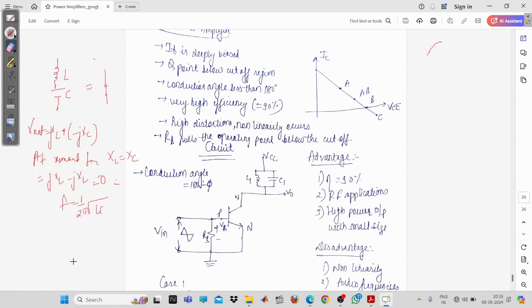Or you can understand the concept from the curve also. We will take the impedance versus frequency curve. This is the frequency. We are increasing our frequency from the DC value, that is 0 hertz, to some higher value. Now you can see that XL will be equal to what? 2 pi f into L. So when you are keeping the inductance constant, normally once you design your inductor, your inductance will be constant.